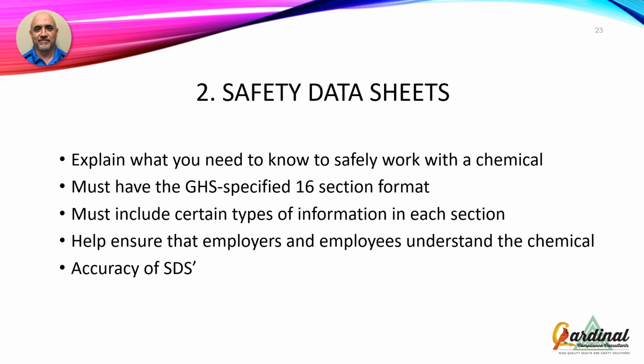And anybody who's ever looked at a safety data sheet, and I don't know if there's anybody on this call that has outside of training, but if you look at the protective equipment, and let's say, to use Zach's example earlier, he should have worn gloves when he was using a stripper. Or he did use gloves, but they had a hole in it. Yep. Well, now I'm going to challenge Zach: how do you know that you had the right gloves? Because if you look at a safety data sheet, all it's going to say is use rubber gloves.